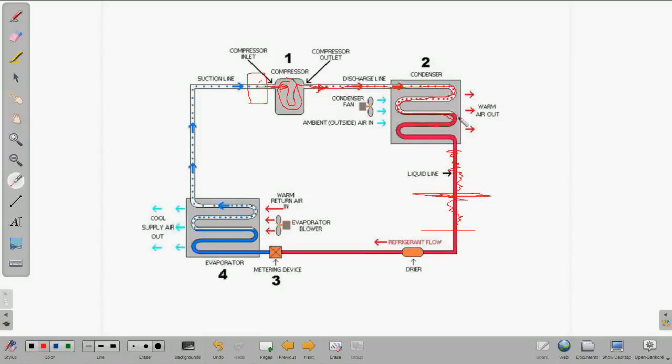And the system is also designed to have this refrigerant back up just a little bit so that there's liquid refrigerant waiting to come out of this condenser coil as the metering device is feeding. So again, an undercharged system with a fixed metering device has very high superheat because everything boils off in the coil and it starts to pick up superheat long before it should, and it has little to no subcooling because it zips through this coil and doesn't start to get backed up behind this metering device until it hits a little bit further down the refrigeration lines.